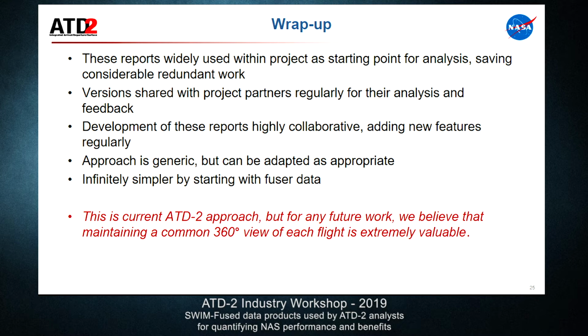I'm not sure who put the question in. Maybe they didn't want to raise their hand. But the question may have also been, how do we decide when a flight has actually entered the queue physically? In that case, we have a geometric approach. We tested an algorithm where you infer that if the flight in front of me is stopped and near the queue, and I stopped, then I'm also in the queue. We've tried that. It was very difficult to get to work right.